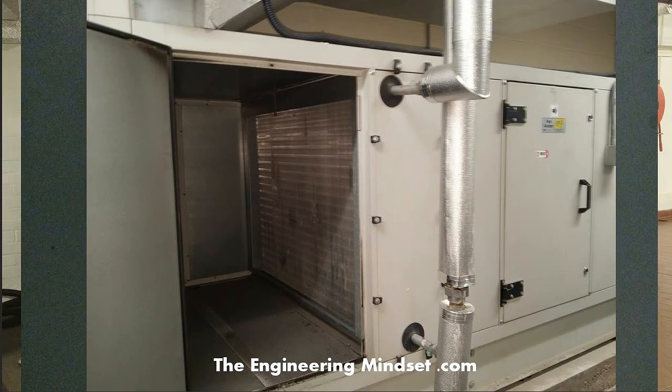So just to show you an example of how a real heating or cooling coil will look, here we've got the connections coming in, and it's just entering there, and you can see these coils are just coming around like that. The tubes are a lot thinner than the ones that I put in the model. Obviously that is just for explanation purposes, to build your understanding. It's a lot easier to visualize it that way. So these very thin tubes actually pass all the way around, and you can see these really thin sheets of aluminium or stainless steel running through there like so.